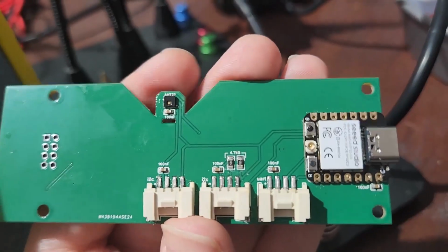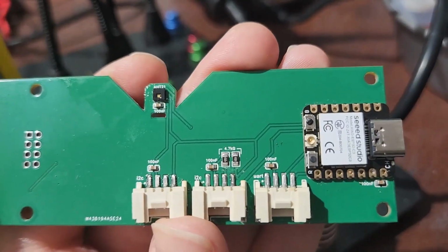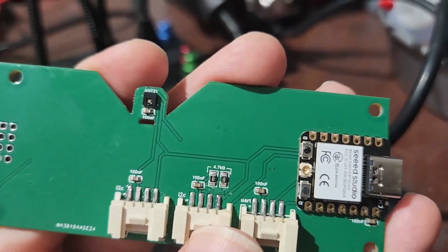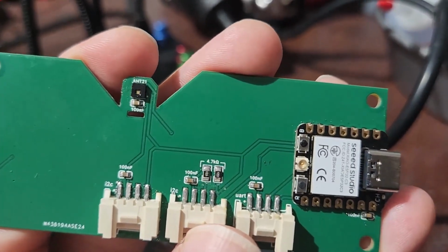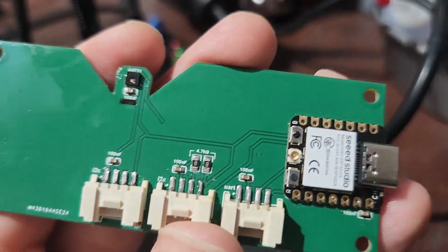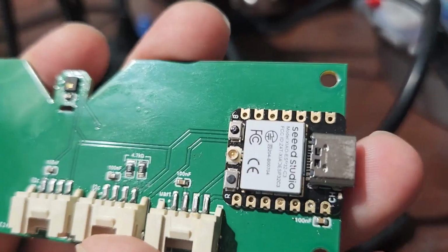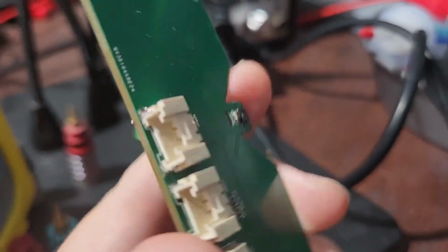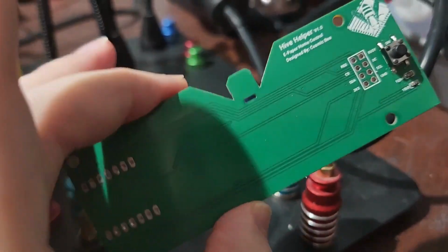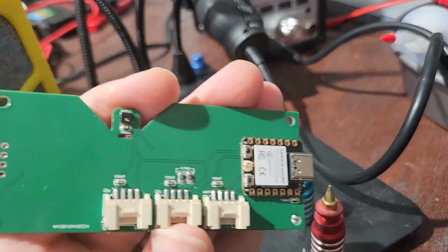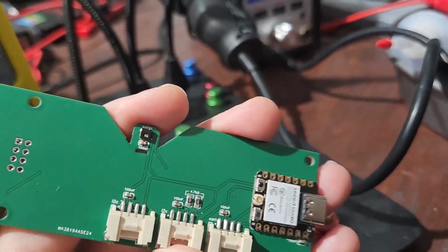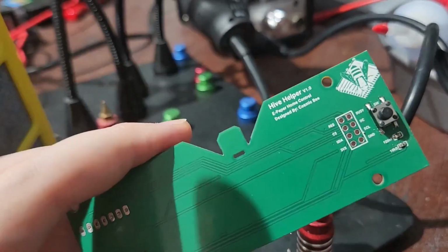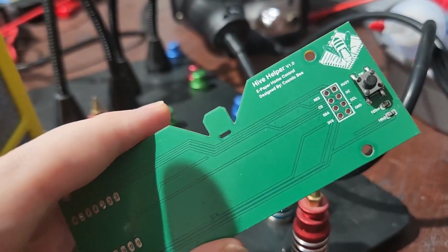To describe some of the testing I did, I checked SDA and SCL to make sure there were no shorts under them, assuming the AHT21 is correctly set up there. In addition to that, I confirmed that there were no shorts between any of the pins on the Xiao here. So now it looks pretty good. I guess I'll test to make sure each of the lines, or the wires rather, are correctly connected to these pins here. I guess, it's fine.